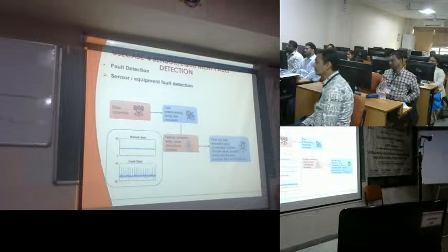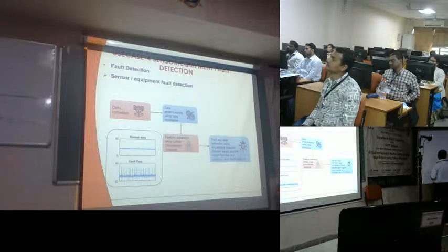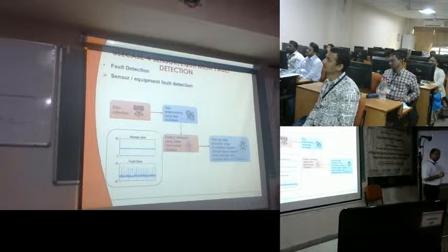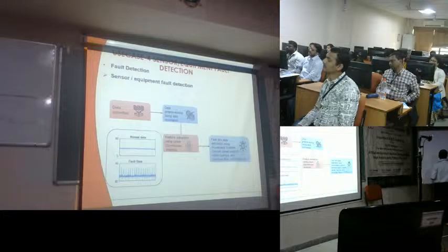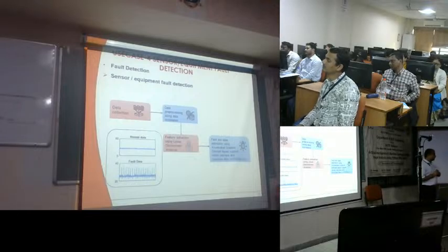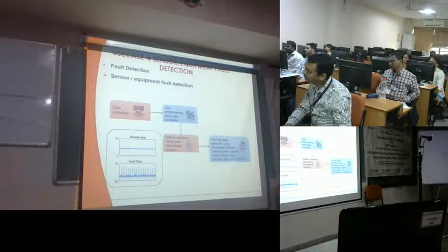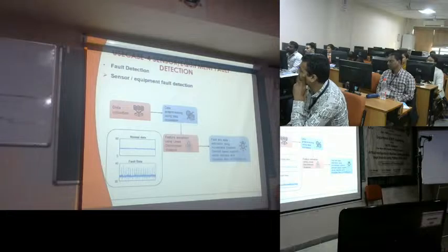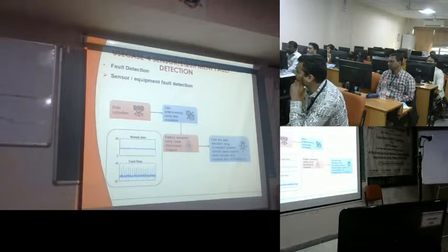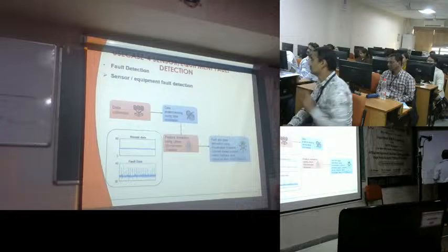So what I can do is introduce one more sensor, S3, and suppose it is giving T2. Then I can apply the majority voting logic, 2 out of 3. Two are giving T2, so that is the actual value, and I can ignore the other one. This is known as triplicated logic, and generally we use triplicated logic.